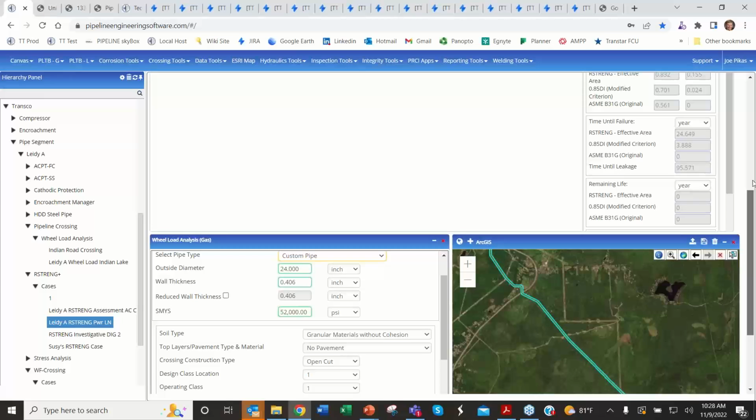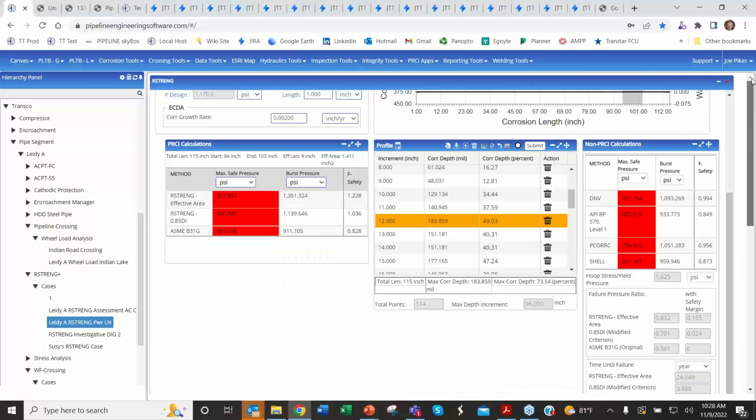So if you have long length pitting such as this, it's about 115 inches long. And I know nobody has 115 inches, but just in case you did run into a situation, or say 40 or 50 inches, you may find that you have multiple effective areas. And this could be a big thing. How do we repair?